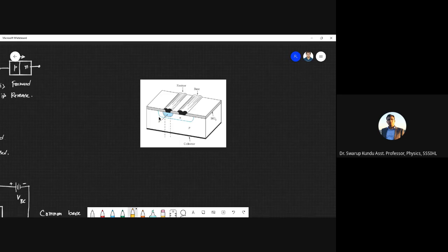So we have basically a P-type substrate, and then we have a lightly doped N region, basically this is the base, and we make a heavily doped P-side emitter later on. And for all this process, we have learned how the diode is made, right? PN junction diode. It's the same process. You mask it, do lithography, etch it, then inject.